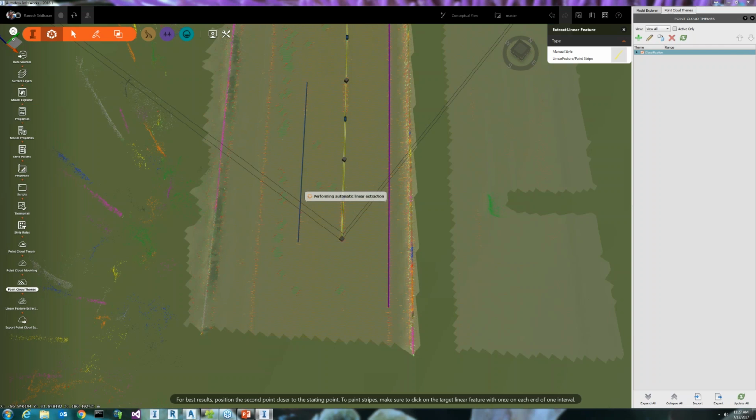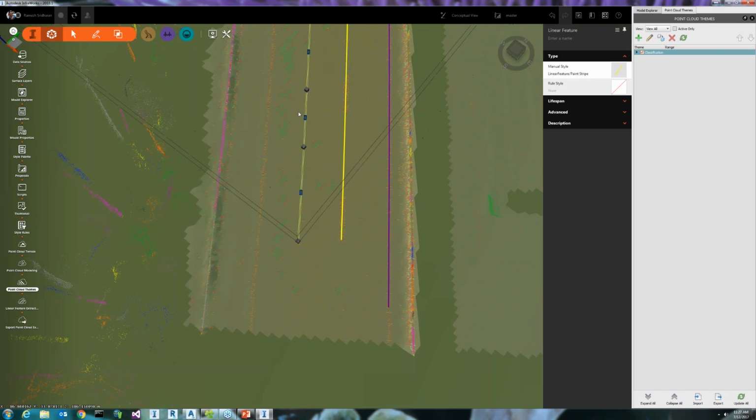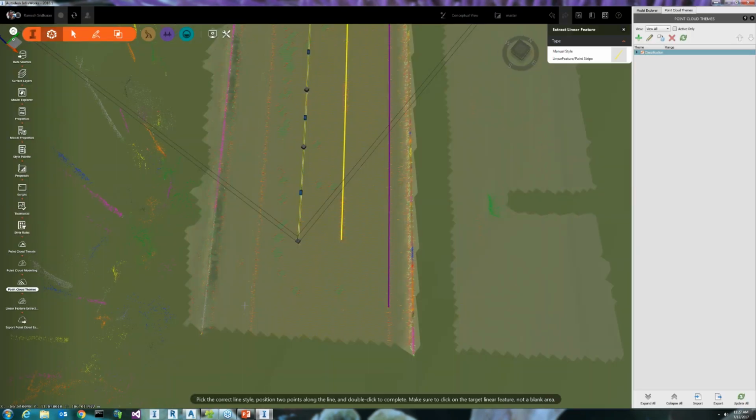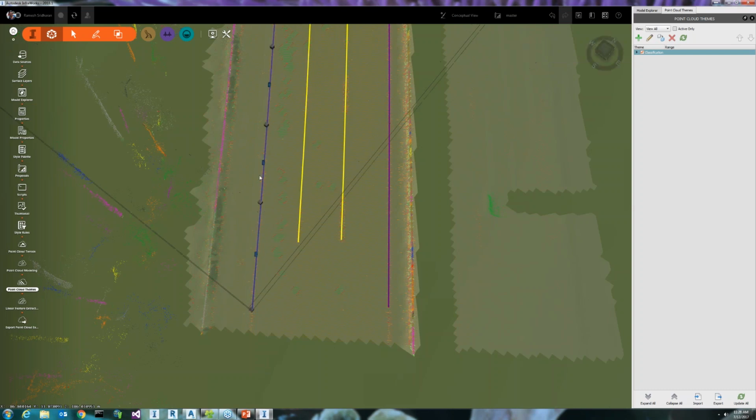And this one, if you know point cloud data, you know there's something called intensity. That's what captures this paint stripe. That is needed for this automated processing. If you don't have the intensity, obviously the software doesn't know which one you're trying to extract, so it might not extract it. But if you have intensity, the software takes care of everything. And even if you have a vague intensity, the software tries its best to classify them and use them to extract. So just here, in a matter of maybe seconds or minutes, I'm almost done extracting my paint stripes.